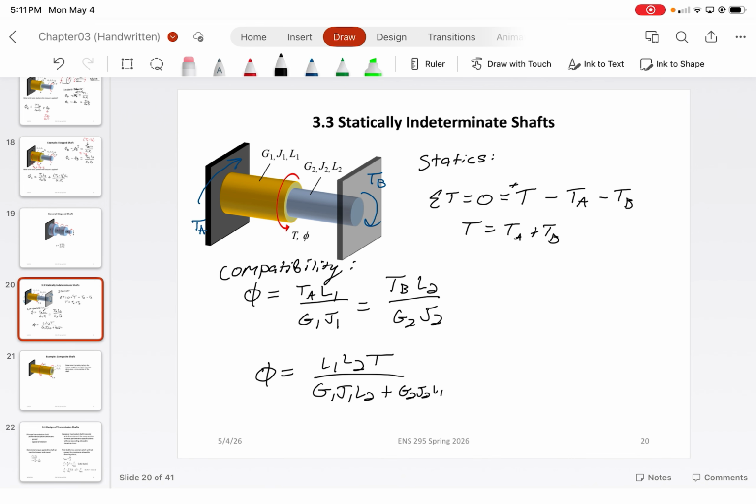All right, now this is just assuming, again, that we're not replacing any of the reaction forces. This is basically the brute force method, just applying a system of equations for compatibility and statics to solve for that final rotation. Again, we need to make some assumptions, such as the rotation at this part of the rod has to equal the rotation at that same point for that rod. And then you just solve for the torques TA and TB and solve for static equilibrium that way.